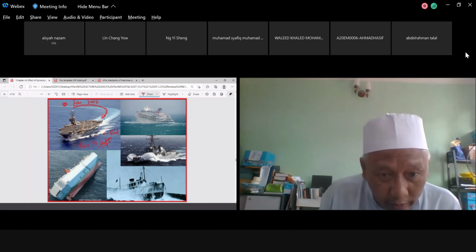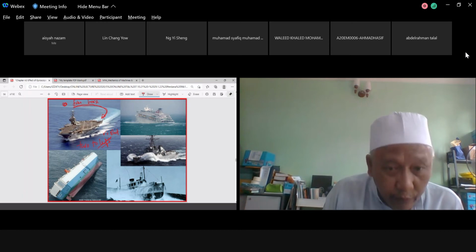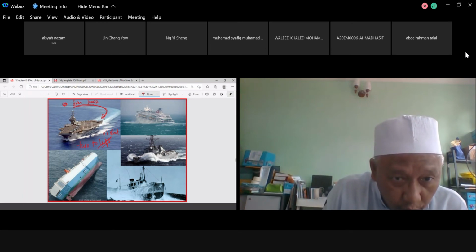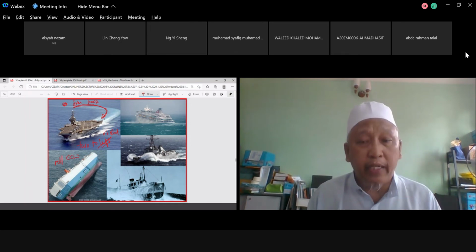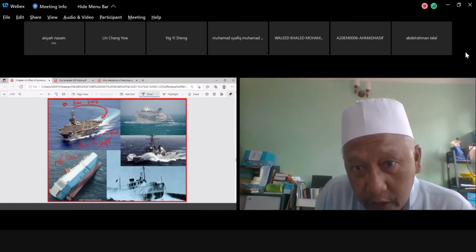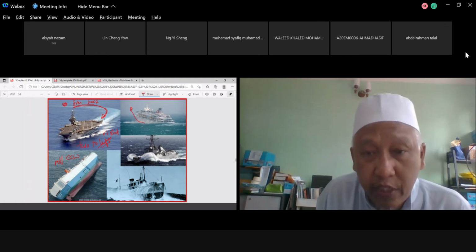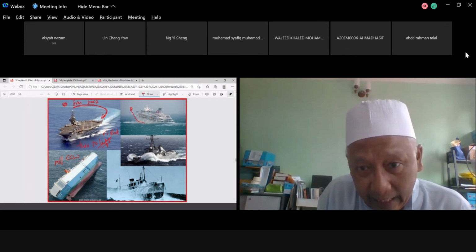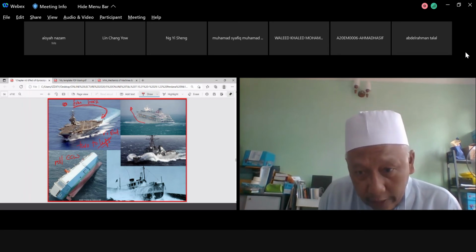This one is roll clockwise or counterclockwise? When you look from the stern, it rolls counterclockwise, isn't it? But when you look from the other side, this one will roll clockwise. So it depends on where you view the ship. This one, when you view from here, will be pointing upward. The boat is ascending, pitching up. When you look from here, the boat will be descending, pitching down. This one is the same thing.